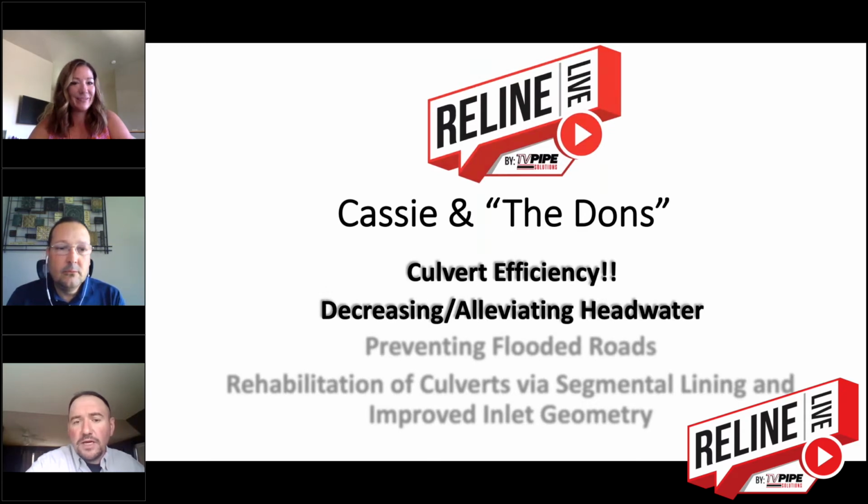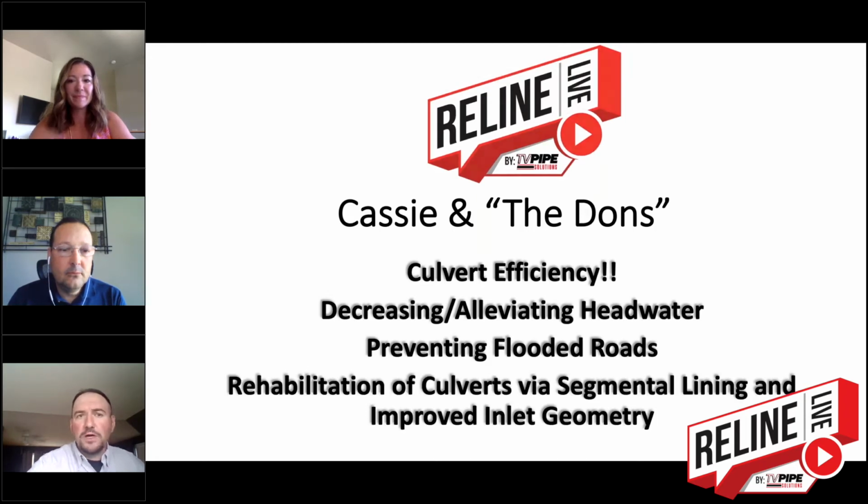Really, what we're talking about, guys, is decreasing and alleviating headwater. When we talk about relining a pipe, usually with a segmental liner, be it high-density polyethylene such as Snap-Tite, or profile wall HDPE, or metal pipe, or any other segmental liner, typically what we are doing is decreasing the waterway area, because we're putting a pipe within a pipe most of the time.